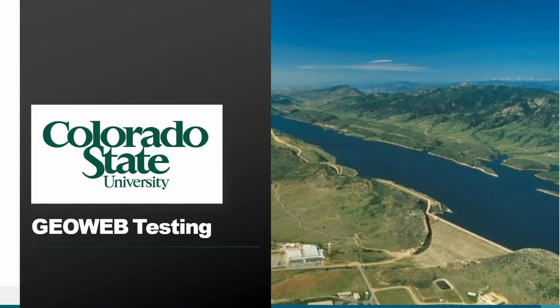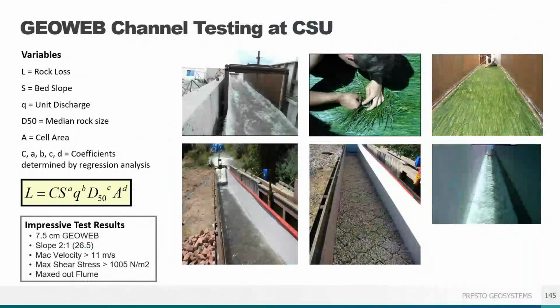We trust the GEOWEB system and have the experience and research to back us. We did a big series of channel armoring tests at Colorado State University under the direction of Dr. Chris Thornton. CSU is considered one of the top hydraulic research facilities in the world, and their lab has a couple hundred feet of static head to achieve extremely high velocities and shear stresses in both their indoor and outdoor test flumes, with impressive results for vegetated, aggregate, and concrete channels. Let's get into some technique tips for each.